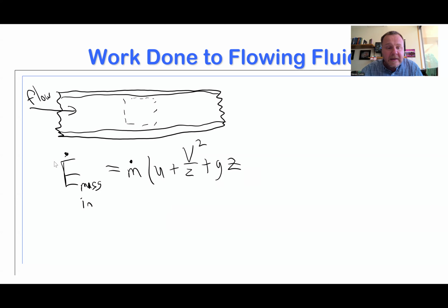What we find is in an enclosed system, your textbook likes to say, pretend that the fluid upstream is acting like a piston, pushing that fluid downstream. And it's doing that by pressure. Now, pressure itself is not energy. Notice these are all energy per unit mass. Pressure is not energy, and it's not energy per unit mass. I need to use something to make it energy.